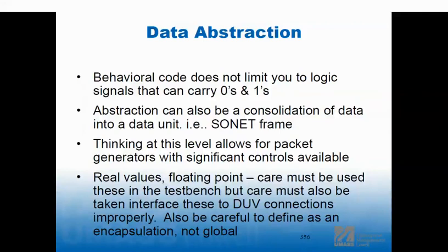So we have in this message, I rattled off source address, destination address, length, whatever, a whole list of things. If it's this kind of more functional bus functional model, we're also going to put things like error insertion. We're going to put randomization in. So when I said that I want a payload with random data, that's a flag that I send across this task call that runs a random number generator in the bus functional model.